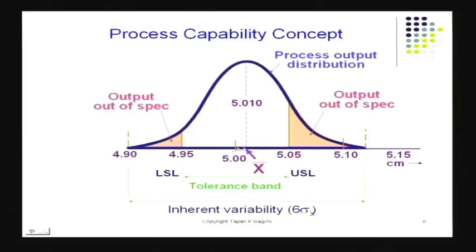And that's going to be my tolerance value. If I supply products that are in this range, I'll be pretty happy. Of course, I'll be most happy if you supply it right at the target. But I'll accept things that fall within the upper spec limit and the lower spec limit. And this is my tolerance band. This is what the customer conveys to you.